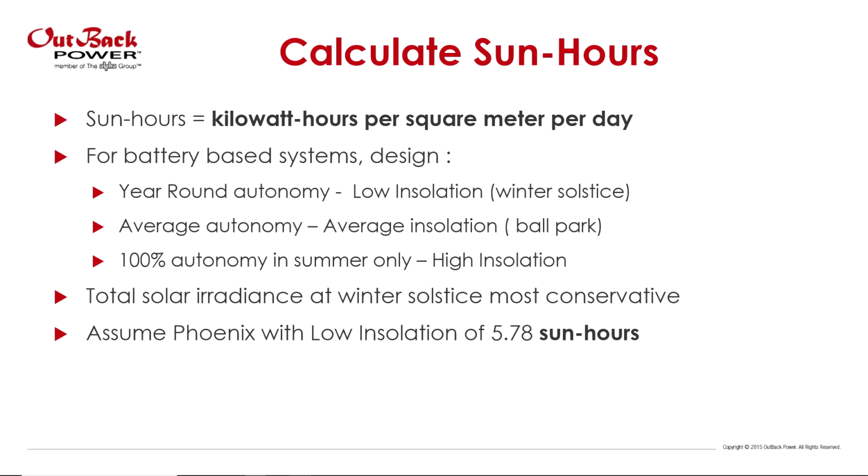You would just need to make sure that your solar array was sized enough to keep the batteries at float so that they don't go bad, but you might not need to size your battery bank or solar as much if that was the application. So that's just something to note.